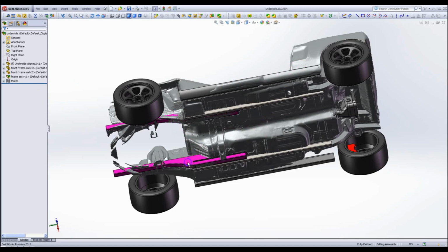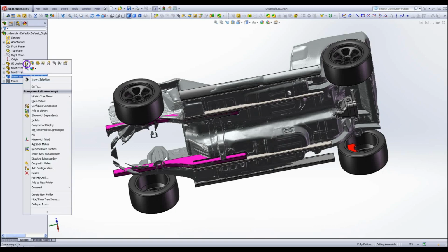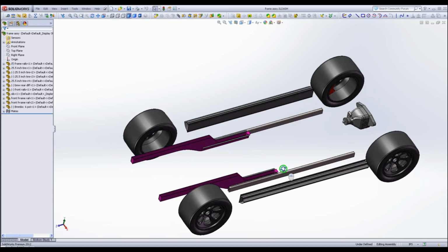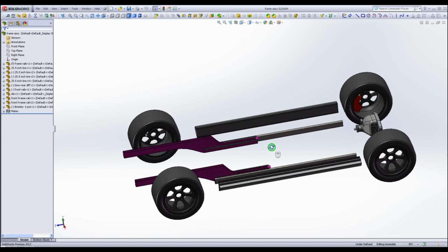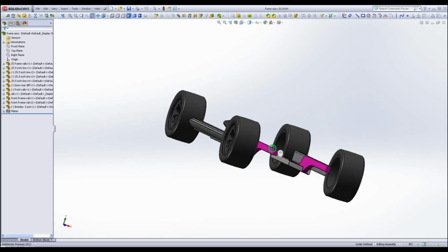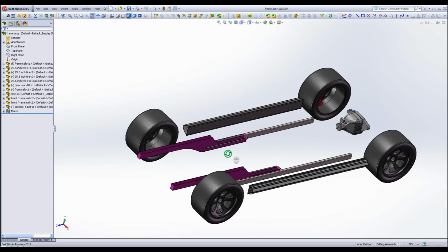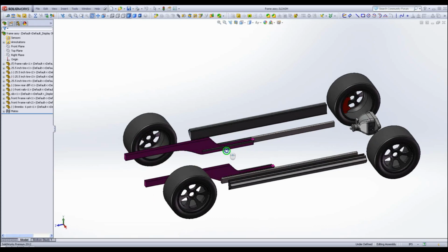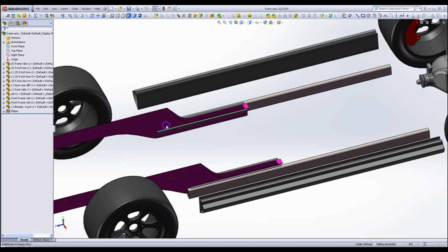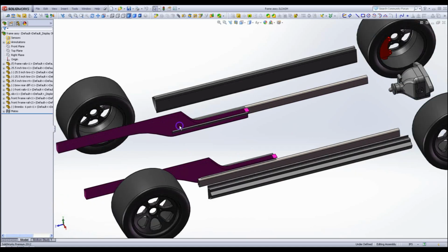And as you can see, in this scan, these purple things are the frame rails. And then I have this frame assembly. Pop that open, which is that. And then this is easy to work with, right? Everything's light. These are just crude approximations of, whatever. And I can manipulate these around. The zero's in the same spot. So basically what I'm using the 3D scan for is to visually look for clearance issues in 3D space and also position these frame rails, right? This is what the frame rail looks like in the car.